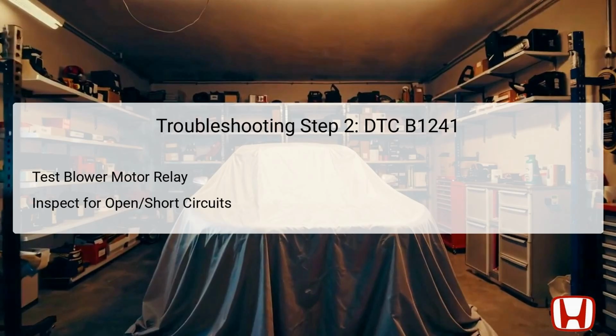First, disconnect the blower motor relay from its socket to perform voltage and continuity tests as outlined in the diagnostic manual. After disconnection, check the female terminals in the relay socket for proper voltage supply and connection integrity. Use a multimeter to ensure that there are no open or short circuits present. Conducting these tests will confirm whether the relay is functioning correctly and whether it is capable of supplying sufficient power to the blower motor. Document your findings, as faulty relay conditions may necessitate replacement to ensure proper circuit functionality.